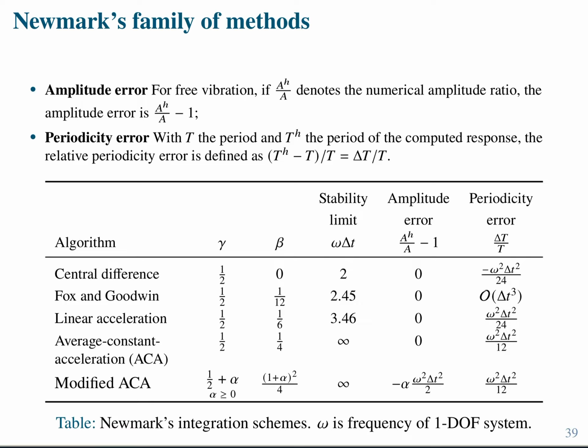Well, I have a good argument, right? Probably not, but then we check, right? We can reduce the time step. We can make sure that the energy lost, because many of these techniques are not conserving energy, is so small, right? Because I reduce the time step so much that I can guarantee that, let's say, the moment I enter in contact with the wall, I conserve the energy or most of the energy. Otherwise, it's just getting garbage. So you have to be very careful when you are dealing with explicit integration schemes, right?